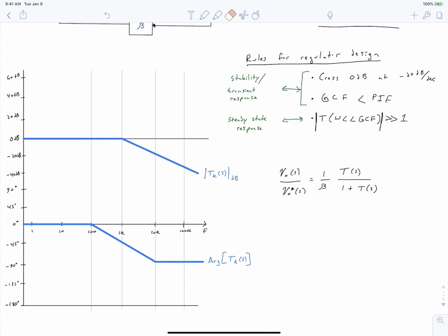And we've also talked about stability in terms of the roots of the closed loop transfer function and how you can determine that from a Nyquist plot and a simple test of the Bode plot, which is what we're talking about now. But at the moment, I want to give a little bit more physical meaning to what happens when we have a phase inversion.